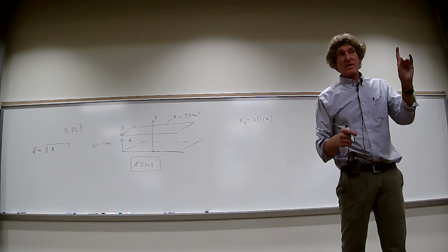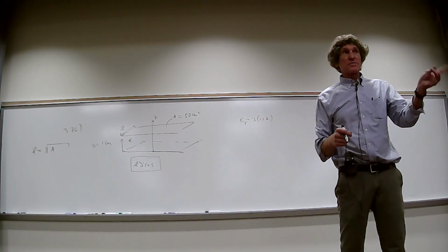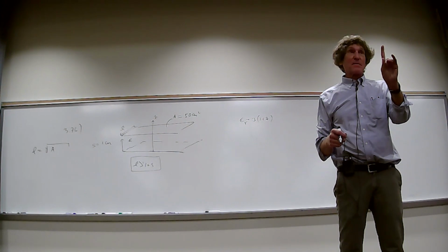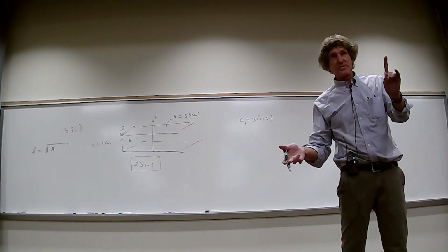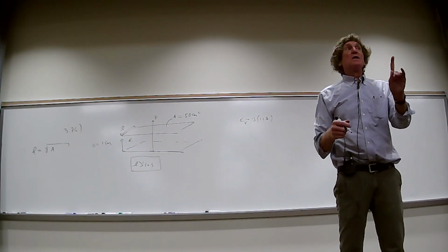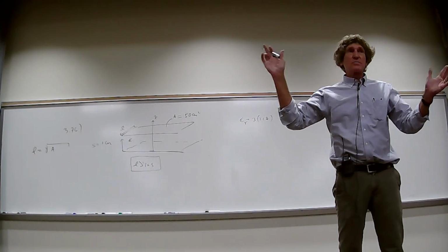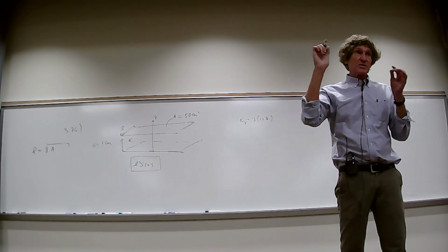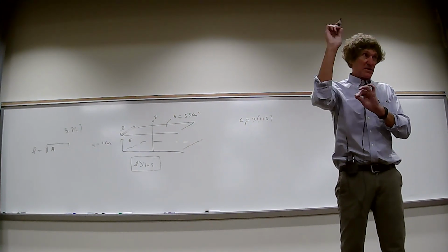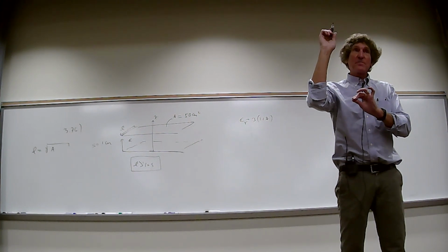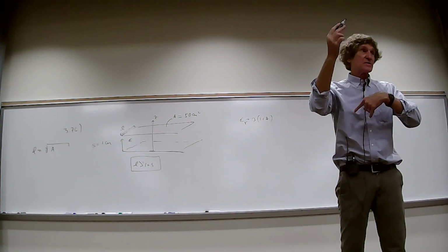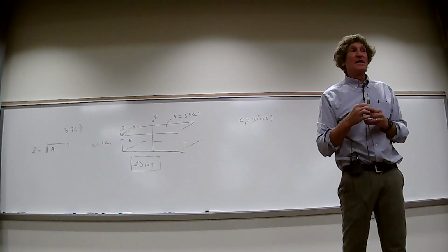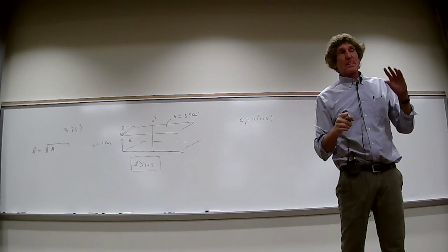Now, you know what a microwave does, right? It takes H2O molecules, flips them back and forth and heats. Well, it can happen to an electrolytic capacitor. So they give you all these warnings: do not have any kind of current in the opposite direction of polarity. So you have a plus and minus. And if you do, God help you, because they'll blow up. You'll literally start heating that dielectric and they will blow up. I've seen the aftermath of these in large capacitors. It can be lethal if you're close by.